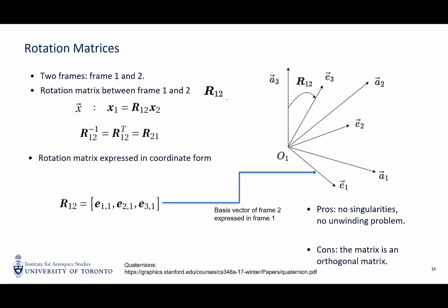The other way is needed because if you use Euler angles, you run into an issue called gimbal lock, which means there is a singularity when the pitch angle reaches 90 degrees. In order to avoid that problem, especially for controlling a drone with very large and agile motions, we need to use alternative ways. A very important one is to directly use rotation matrices to describe the attitude.